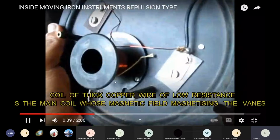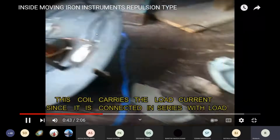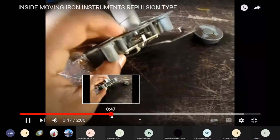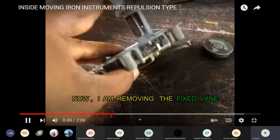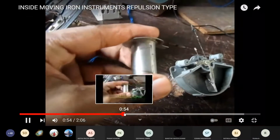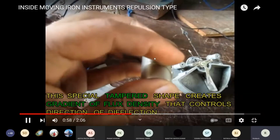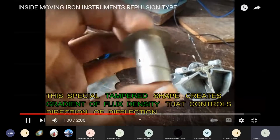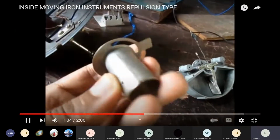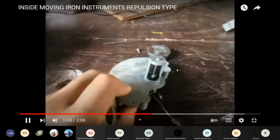So you see the coil. This is the coil through which the current flows, which we are trying to measure. And then within this is a fixed vane. This is a fixed part of the moving iron type, and it is tapered. As you can see, this is tapered to generate a linear motion, the linear variation in the repulsion plate.